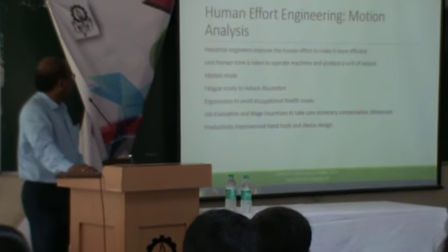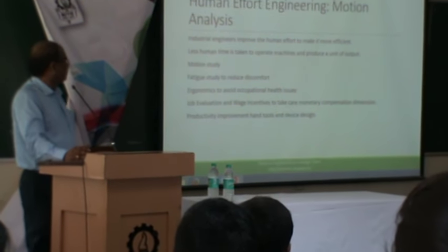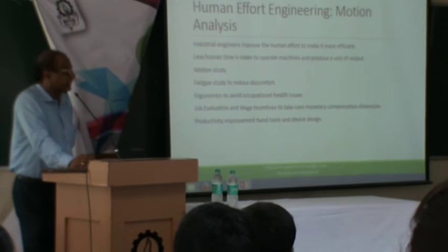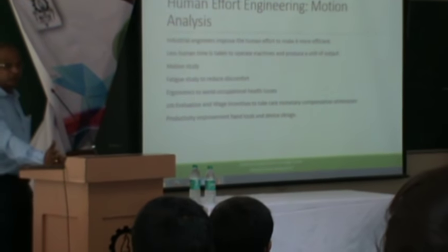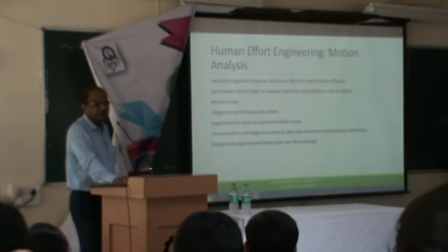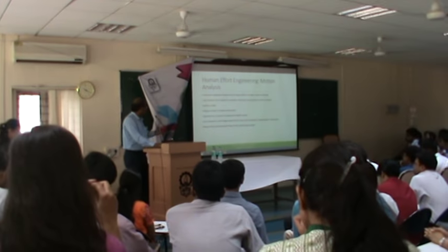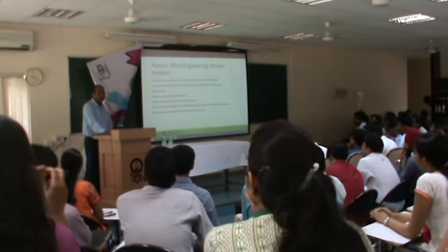Then we are coming to human effort engineering. This covers motion study, principles of motion economy, and fatigue study, which we need to do. We said 57% is rest and 43% is the working time that you are going to do. Economics: you have to make sure of job evaluation and wage incentives.